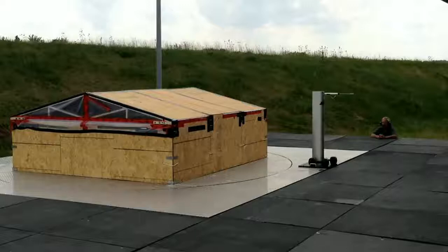The test specimen is placed such that the ridge of the roof is perpendicular to the direction of wind flow. Visible here are the 4 trusses and corresponding roof-to-wall connections along the windward face of the model. As fan speed increases and suction is induced over the roof, displacement will occur at these locations. Wind speed is measured by the upstream Cobra probe mounted at eave height.